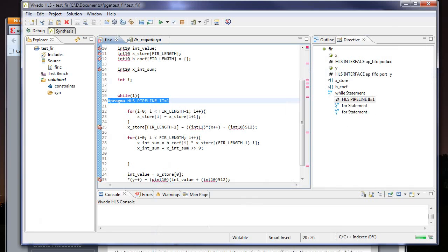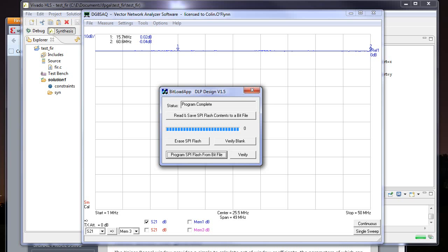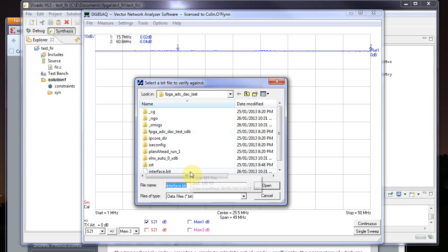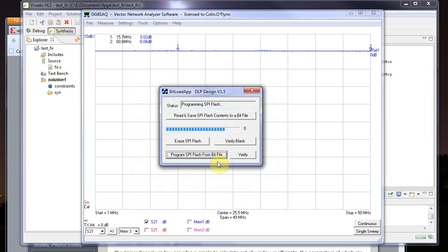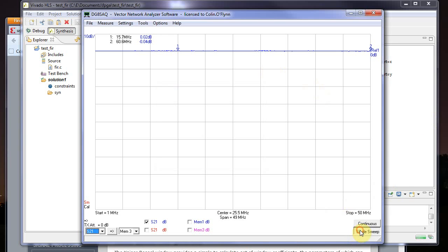Returning back to this project, remember I had just inserted the delay line in here. So I was just checking that the X values were working properly. Ideally, you can do this all through test benches, and you can get some nice simulators that'll interface with MATLAB for helping you do some of the test benching. I'm trying to show you just the HLS stuff now, so I'm sort of skipping out on that. And again, it's worked. We see that there's a little oddity somewhere, but basically it's worked well enough.